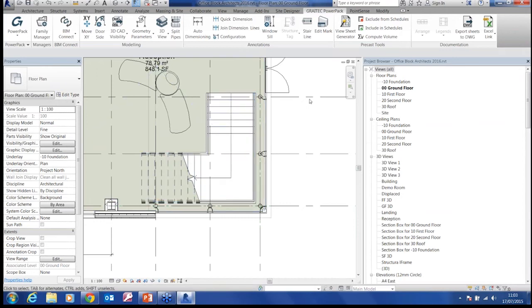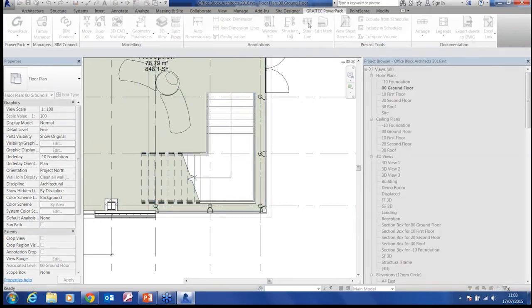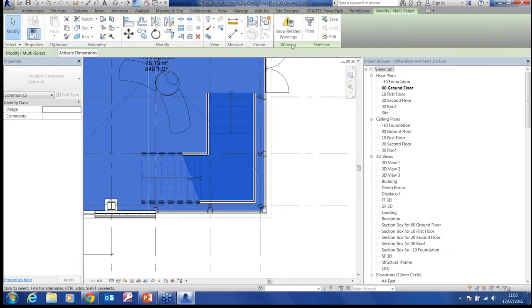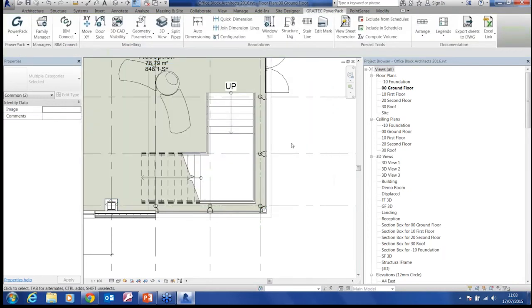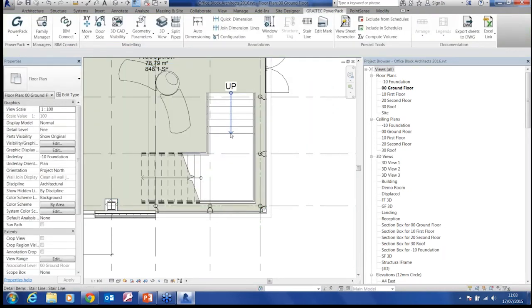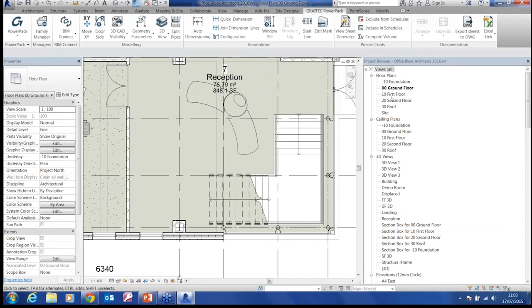So what I can do is I can go to my stair tool. I can just select them elements. It doesn't really matter the fact that it's got rooms in there, because it's detected now the stair look, and it's put the line up to them, and it's drawn the next line there. If it was a continuous stair, it would draw it all the way to the top.